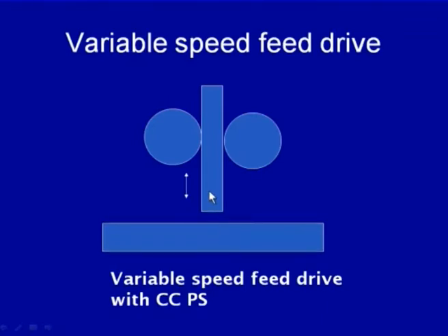To take care of these fluctuations in arc length causing the change in arc gap, the arc voltage will be changing. This change in arc voltage is used as an input for changing the current value being used for driving the motors of these feed rollers.